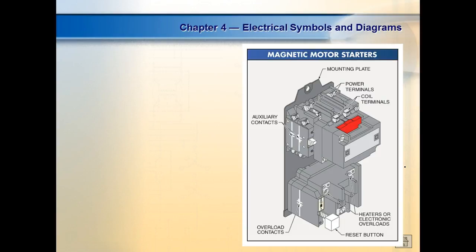We need to do a lab here pretty soon. I'm fixing to stop. Let me find this. This is a stator of a 3-speed motor. It's very common in HVAC systems. So the brown wires are for the start capacitor, guys.